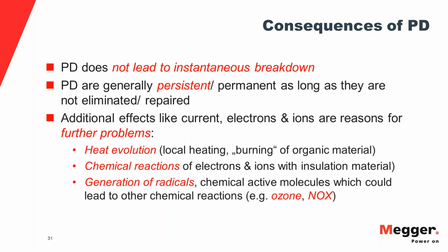And then what's the consequence of PD? The problem here is if you do a VLF test and a VLF test only, and that has been established for years, this is no news. Some people run around and say, oh, VLF testing is not finding all the faults. Well, that was clear almost from the beginning, a few years into VLF testing.